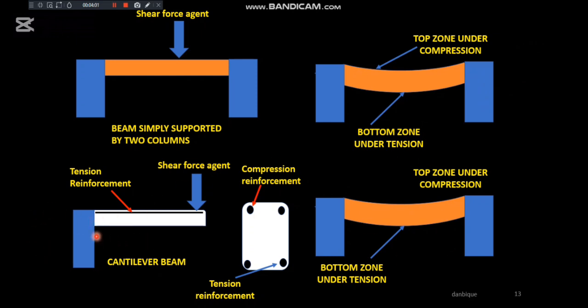Another one is the cantilever. You see that this cantilever is under tension on the upside because there is no support at this level, and so the tension capitalizes on top. So the main reinforcement bar should be placed close to the top, which is why I told you it is not just to know you have to use reinforcement in your structure, but to know where to place them in order not to make it a waste.